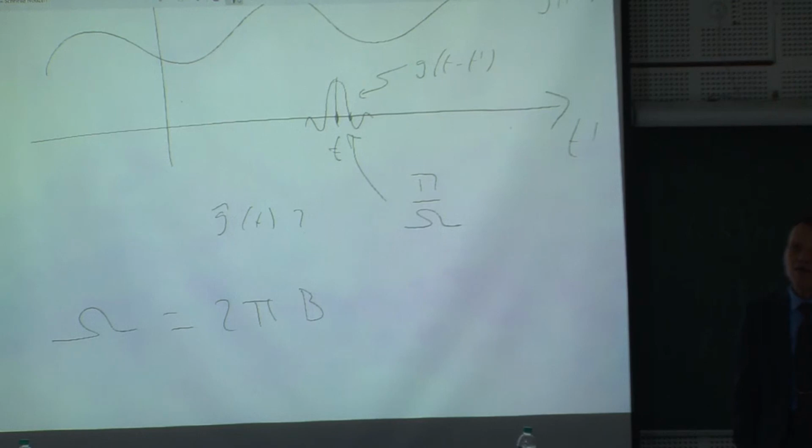Now I think you can recognize what this means. If you look now at the artifact, because now in the imaging, you can recognize how useful this windowing is. In my case here, the window is a rectangular window, right? If I use a triangular window, I will widen the main lobe, but I will lower the side lobes. So my sun, which was a point, will be a little bit bigger. But the two suns, left and right, will be much weaker.